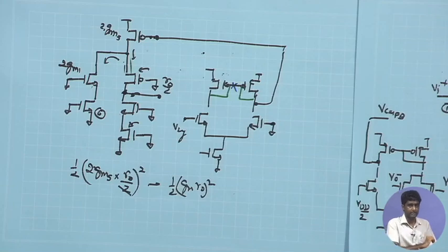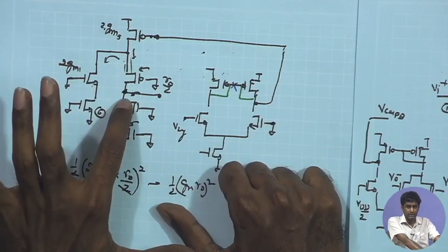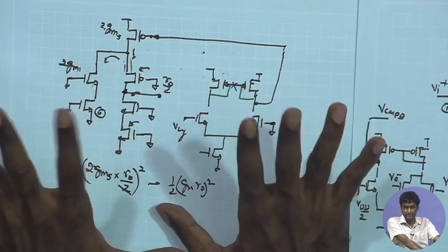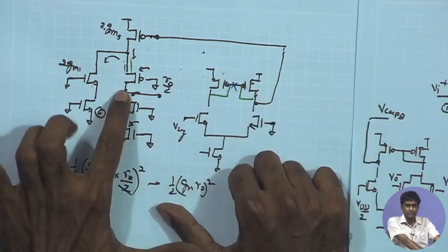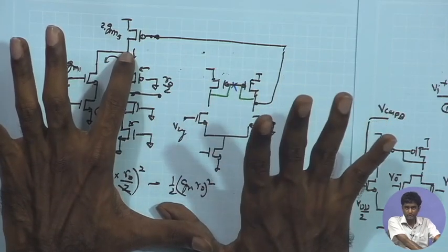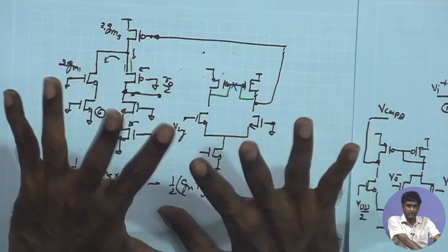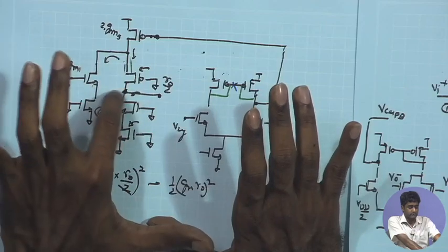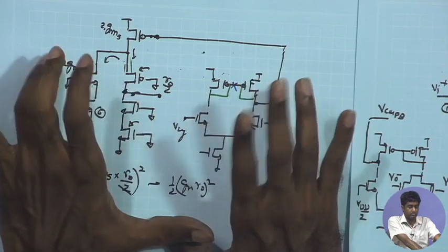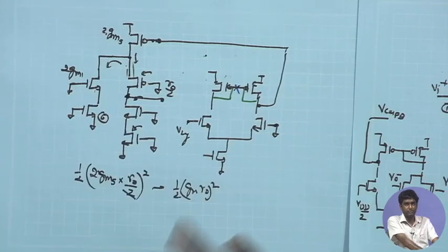That is important to check, because we are assuming that the capacitance over here is small, therefore a nominal capacitance value of a few picofarad is sufficient for compensating that. And if you are assuming that a few picofarad is sufficient, I would have to make sure that the total capacitance over here is not more than say 100 femtofarad. If I am targeting a GM RO of around 100, a few picofarad of capacitor, a couple of orders of magnitude higher than this 100 femtofarad, is able to compensate this.